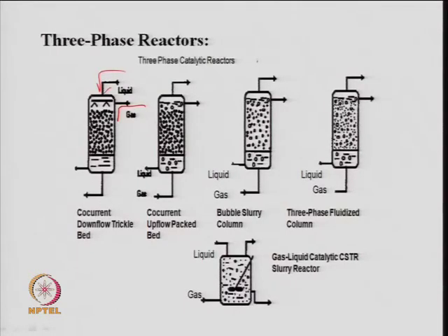This is again a co-current type of upflow packed bed, because the flow can be downward or upflow. So, this is a kind of upflow. So, you can have a good contact between gas, solid and liquid compared to this, because the channeling and flooding problems can be minimized in this kind of system.